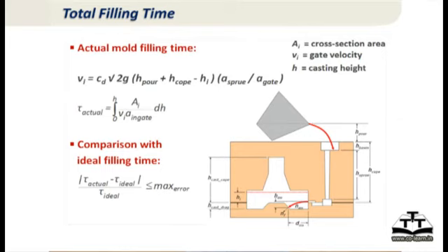Head reduces, so velocity reduces. So as the metal rises above the gates, my head is continuously reducing, velocity is continuously reducing, and cross section areas are changing, but all this can be estimated by putting up an integration. With a simple casting you can do hand calculation, otherwise you can write a simple program to calculate the filling time